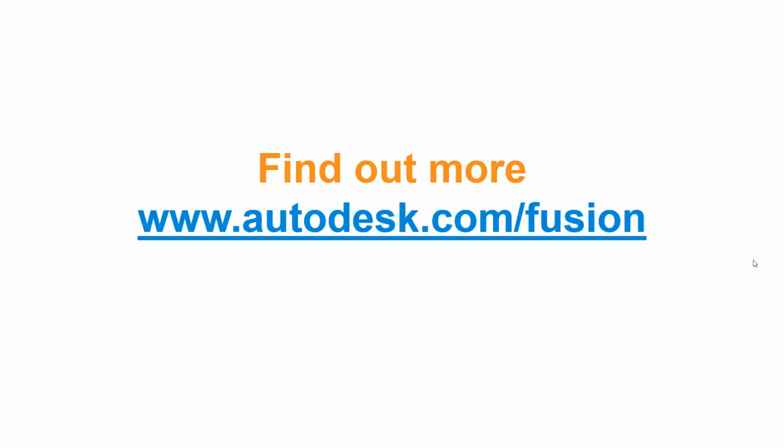Oh, we have got some late questions coming in. Bear with me. I can see it. So, can you do stress simulation on wood? Wood is a non-linear material, so right now, as of today, no. What you can do as an approximation is do a range of static tests across different properties of the wood that will give you some idea around where that will fit. That said, later in the year, for anybody who's into stress analysis, we should be having the inclusion of a Nastran solver in there, which will allow us to simulate non-linear materials. So there will be a solution towards the back end of the year. Oak or pine, yeah, so any wood really.